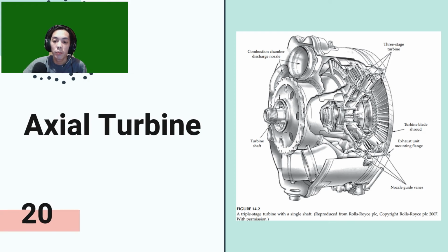Turbofan and turboprop engines usually employ a separate turbine and shaft to power the fan and gearbox, respectively, and are termed two-spool engines. A three-spool configuration exists for some high-performance engines, where an engine turbine and shaft power separate parts of the compressor. Nearly three-quarters of the energy extracted by the turbine is used to drive the connected module, which is the fan and compressor.